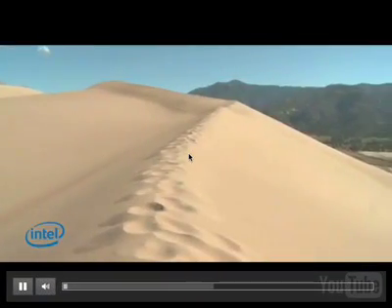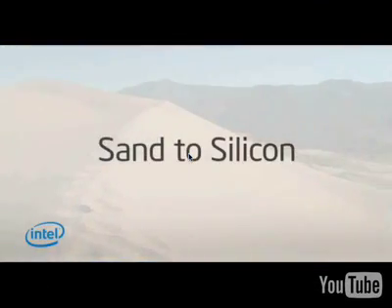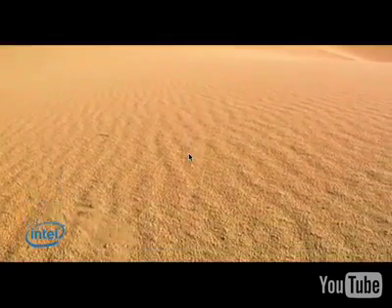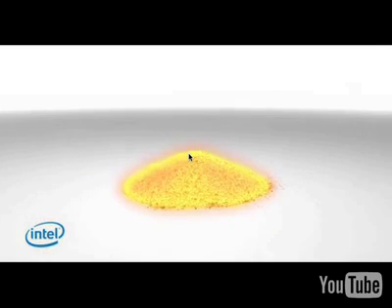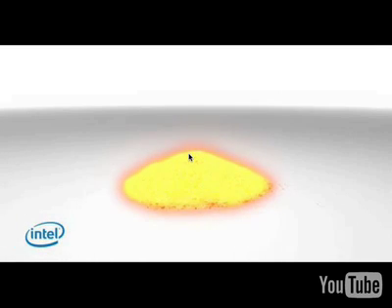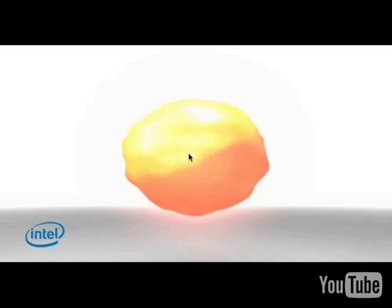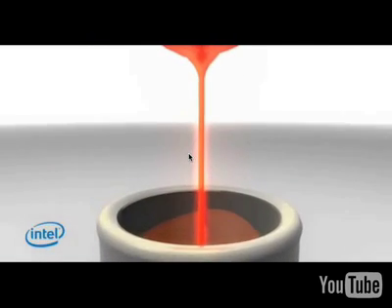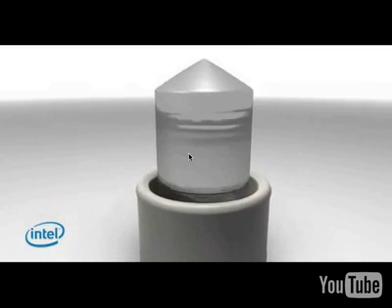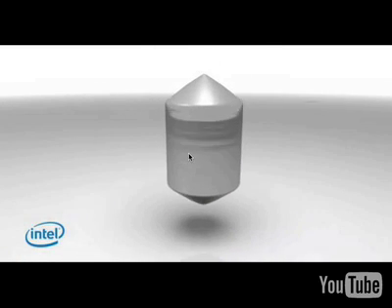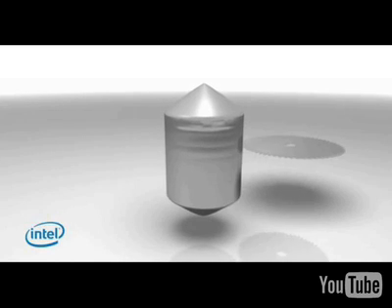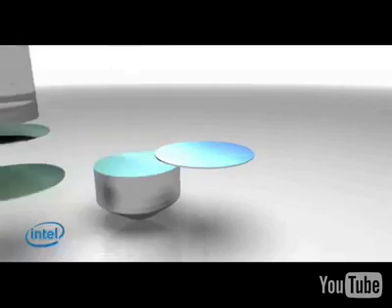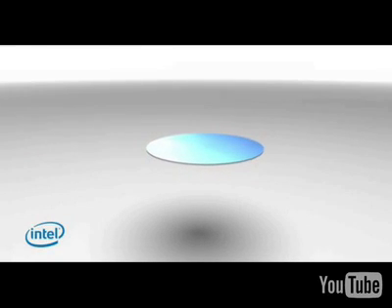Okay, so essentially this is from Intel. It talks about sand to silicon. So of course, all integrated circuits start with silicon, and silicon comes from silicon dioxide, which is sand. Very ubiquitous, very cheap, easy. It's melted down. We talked about this. Okay, it's purified. When you melt it, you can remove impurities. You essentially form these big cylinders. Okay, it's called an ingot, I-N-G-O-T. You get these big things. And essentially, this gets sliced up with a diamond saw into very thin silicon wafers. And I have one of these, which I will pass around at the end of this video. Okay.